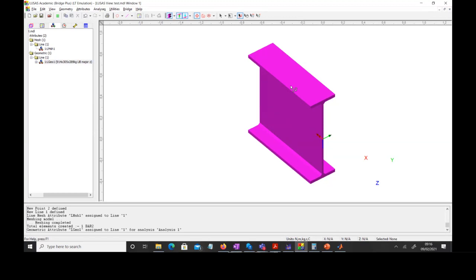And by same material properties, I would mean the same yield strength. So the yield is going to be the same for any direction you hit this material from. Now you have some loads, and you can now compute the stresses, and you want to check if this cross-section is going to yield or not. Let us simplify the discussion. We want to figure out if this cross-section is going to yield or not, and we want to check that.